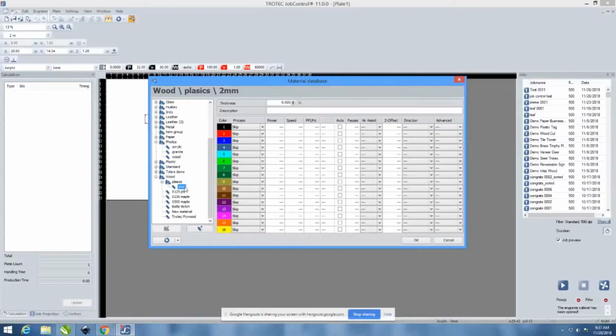So like Lev said, you'll want to run that grayscale matrix to find out the perfect settings. It doesn't just have to be the matrix. You can literally engrave a half-inch square to test, and then keep engraving it at different power settings if you want. The grayscale matrix just makes it a lot easier because it gives you a bunch of little squares all together at different settings. Yeah, so if you just want to adjust it a little bit, just do one square at a time.